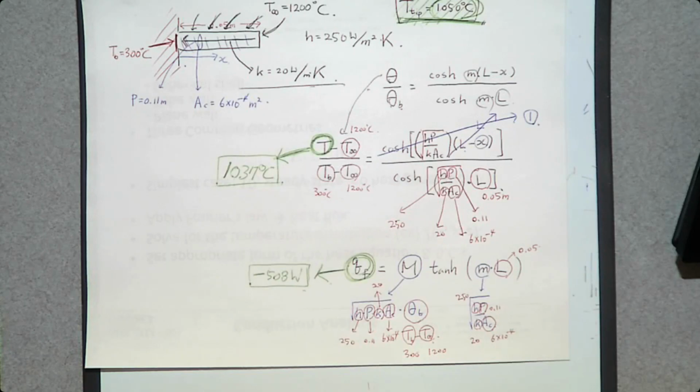Because what matters is that on the surface we assume there is convection heat transfer. The rate of heat transfer by convection from a square shape or a circular shape is about the same, as long as you have the same surface area.